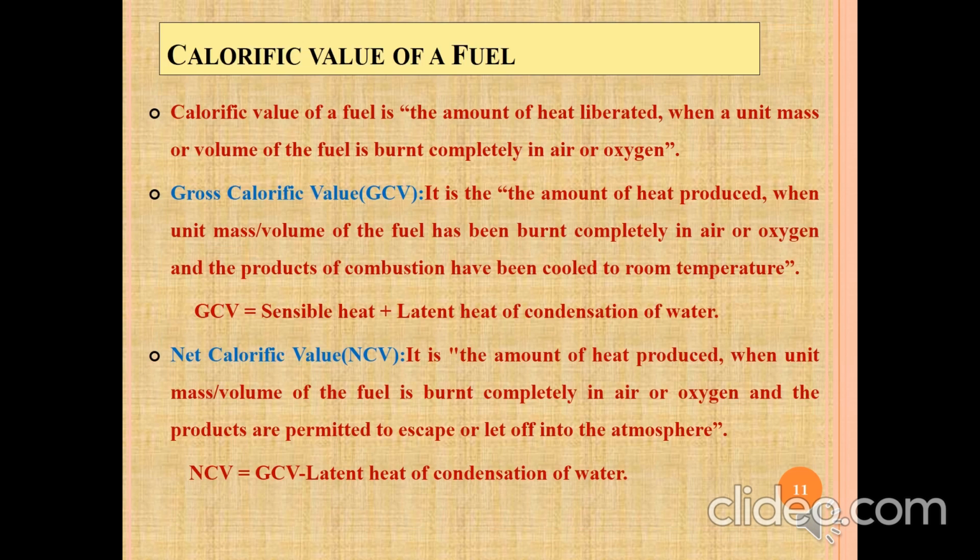Calorific value of the fuel. Calorific value of the fuel is nothing but the amount of heat liberated when a unit mass or volume of the fuel is burned completely in air or oxygen. There are two types of calorific value. One is gross calorific value, GCV, also known as high calorific value. The other one is net calorific value, NCV or low calorific value.